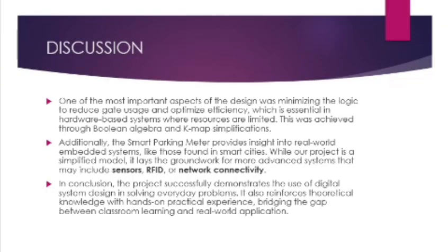So from all of that, the most important aspect of the design was minimizing the logic to reduce gate usage and optimize efficiency, which is essential in hardware-based systems where resources are limited. We can achieve logic minimization through Boolean algebra and K-map simplification.